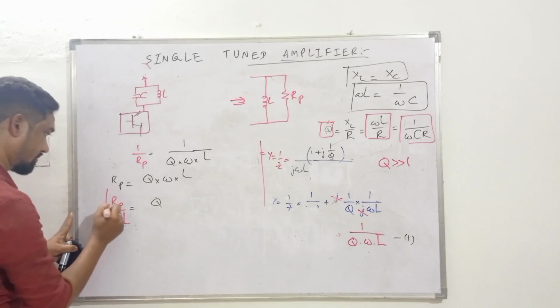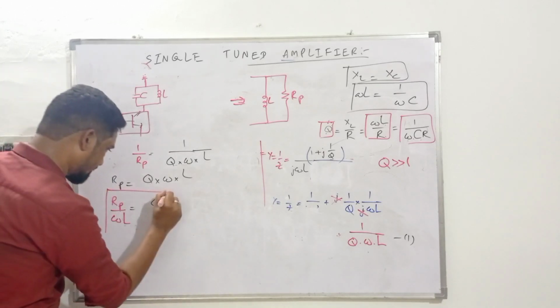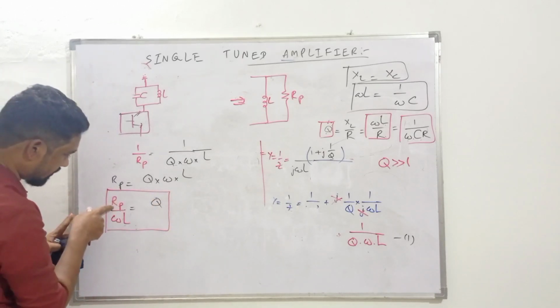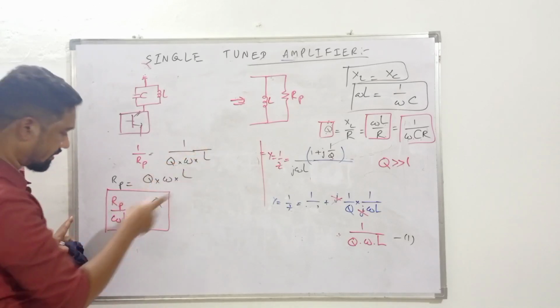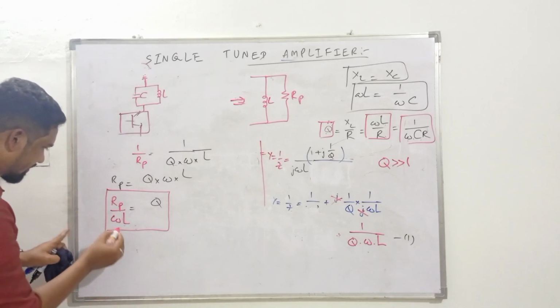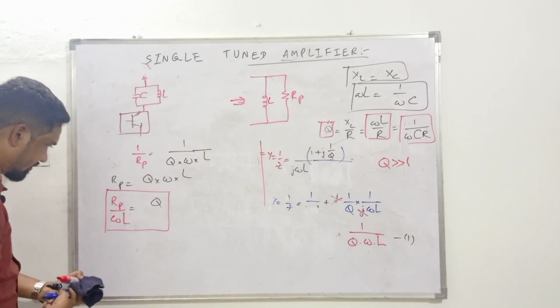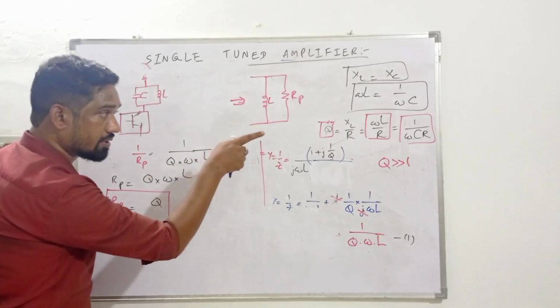So guys, I didn't manipulate this, okay, I'm not saying that this is this, no, we got the expression, and even this ratio will be Q, right? We have those ratios, and yet there is another important ratio also. At resonance, what is this? Omega L will be equal to 1 upon omega C, isn't it?